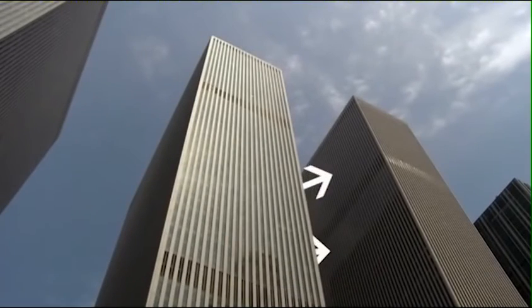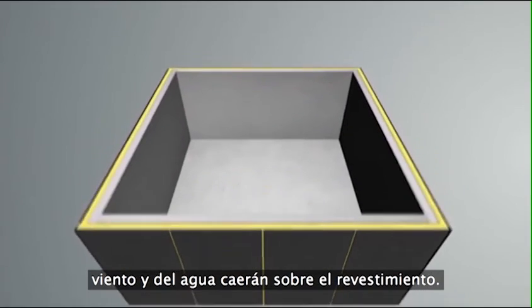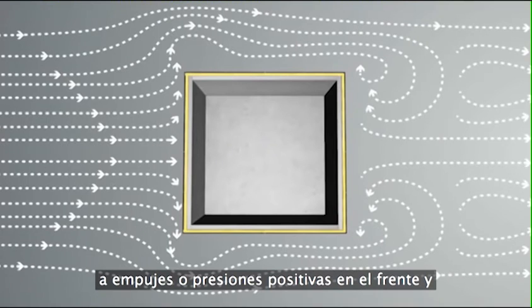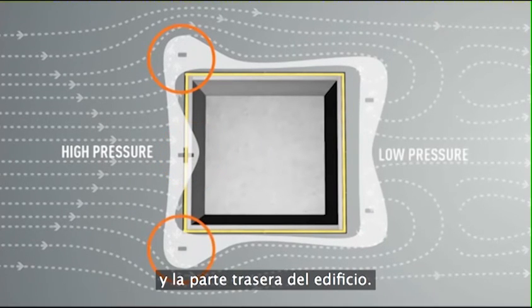The effect of the wind. The main issue is the wind and what effect this will have on the cladding. Wind blowing onto a building will give rise to pushing or positive pressures on the front face and pulling or negative pressures on the sides and rear of the building.